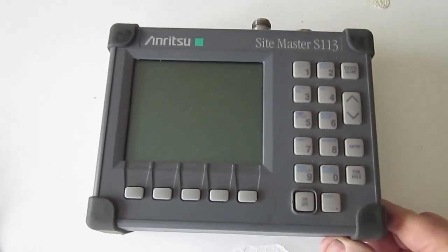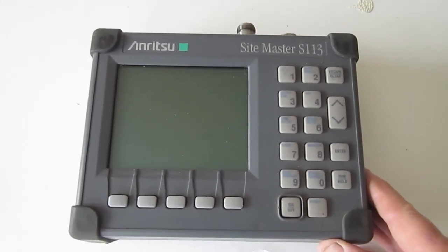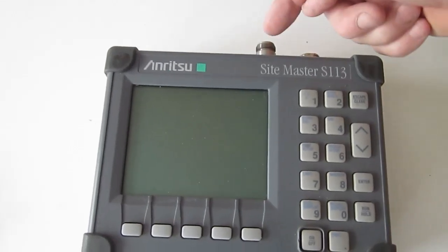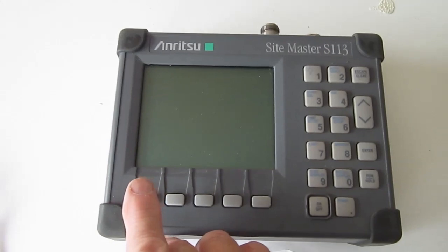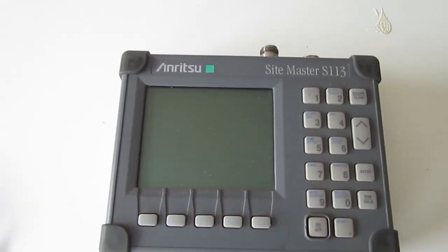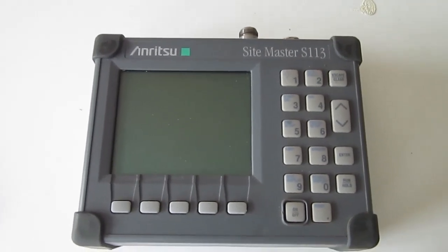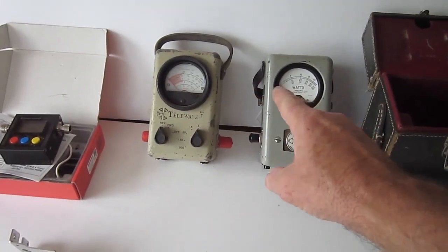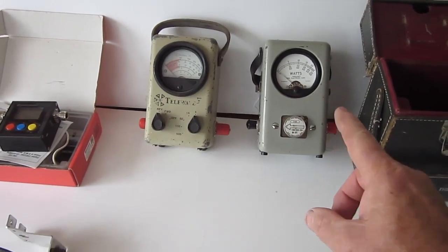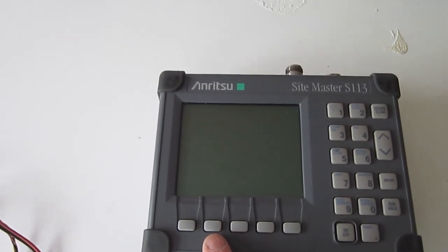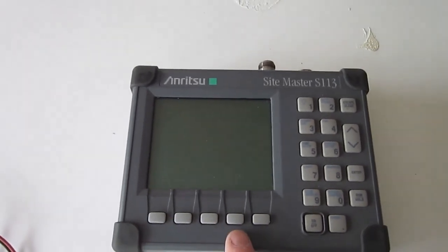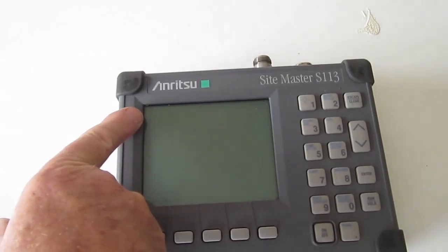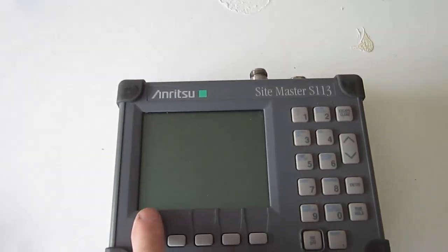This doesn't require the use of the transmitter. This has inside it its own sweep set. So obviously it's going to output a signal from the port, and the reflected energy is also going to come back into the same port, and the meter actually will draw the plot of the VSWR curve, and it's unlike the meters over here, which is giving you an SWR measurement at a specific frequency. This thing is of course letting you know what the VSWR is across the entire band, so it's actually very useful. The SWR of course will be as the SWR increases, it runs up the side here, and frequency along the bottom.